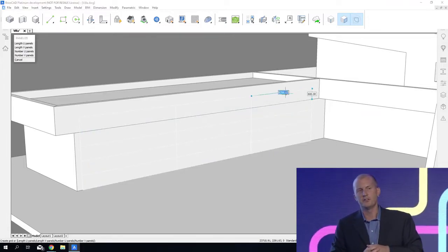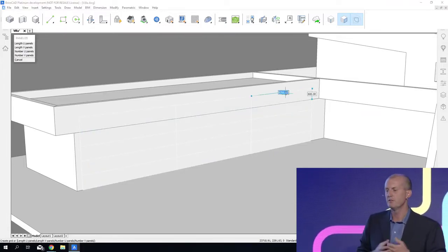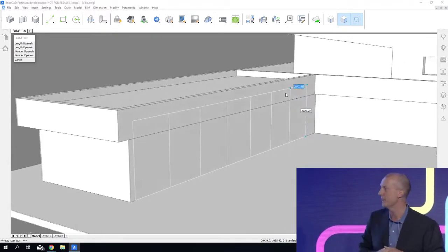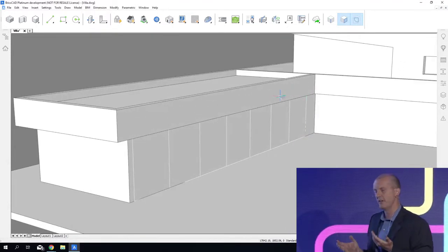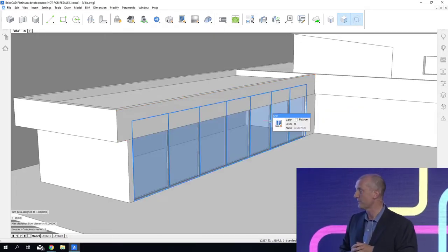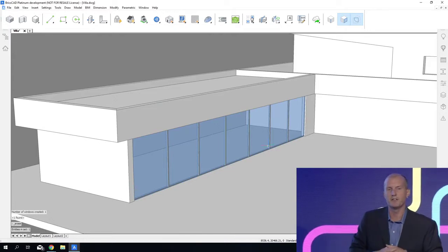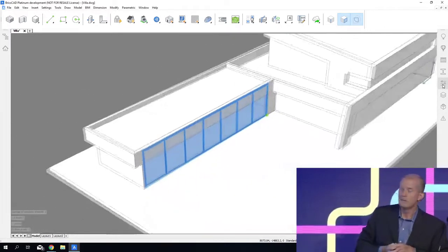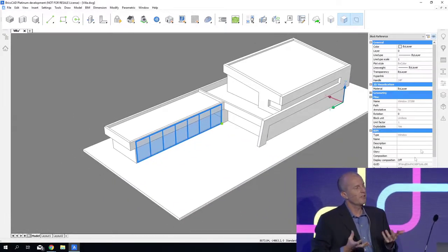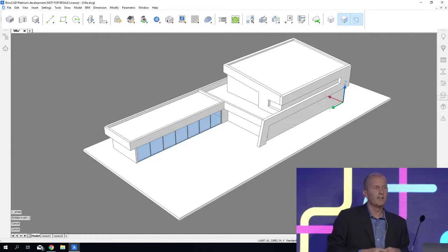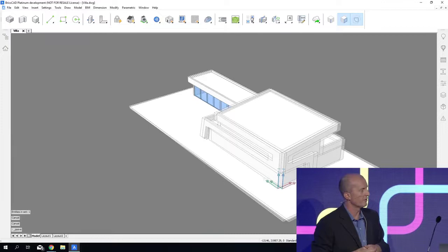And what this allows you to do is you can create a grid. It gives you a default grid, and you can refine the size of that grid however you want. Once the grid's defined, we can use BIM Create Window that we can select from the quad to quickly create this glass pane wall. So check, we're starting to add more detail and shape the design of this building. What are other approaches and ways that we can add further detail to the model?